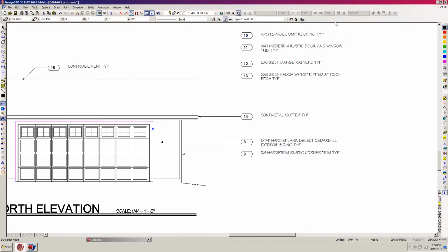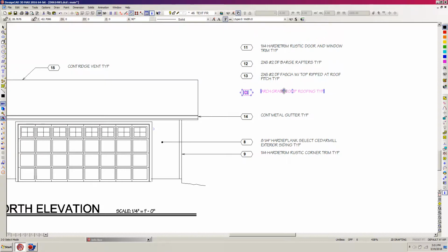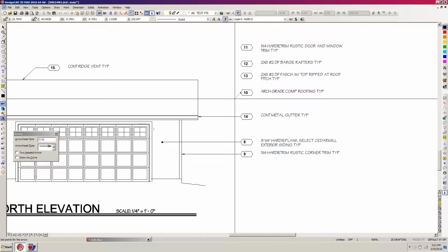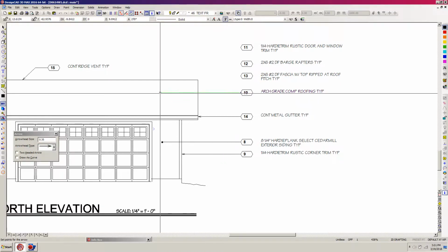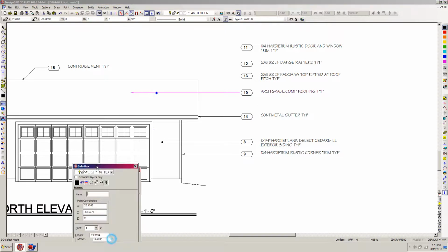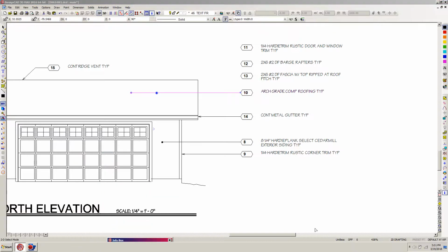So now I'm going to pull my roofing note down, gravity move, M, and just arrow it on down about like so. And I'm going to put an arrow from there, click on the point of the sheet note box, hit H for orthogonal mode, come on over into the body of the roof somewhere, roofing, click and set a point, and I'm going to make this arrow the same type as the dot arrow. So I'm just going to go here and use the same as command, which makes it pretty straightforward and pretty quick to do.